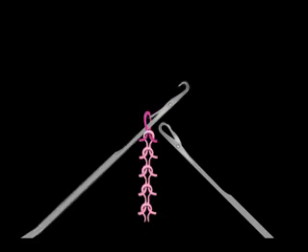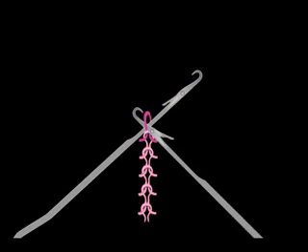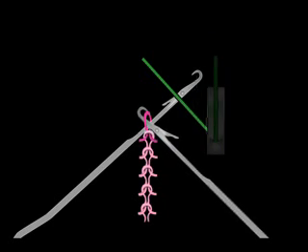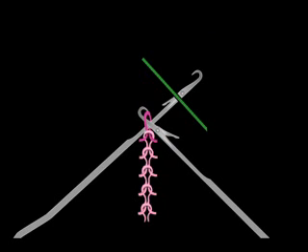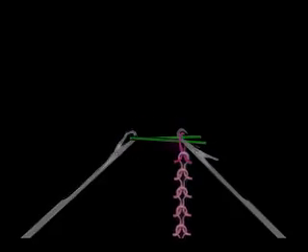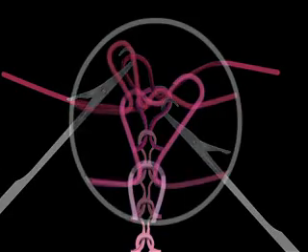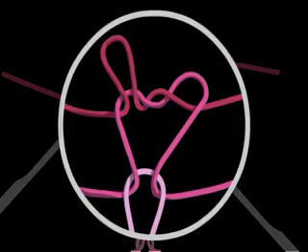Widening or narrowing of a fabric panel or garment can be achieved by the transferring of a stitch or the dropping of a stitch. A split stitch is formed as a stitch is transferred to the opposite bed, but at the same time a new yarn is fed to the needle holding the split stitch and pulled through the transferred stitch. By doing so, a much smaller hole is created in the fabric as compared to just a transfer stitch.